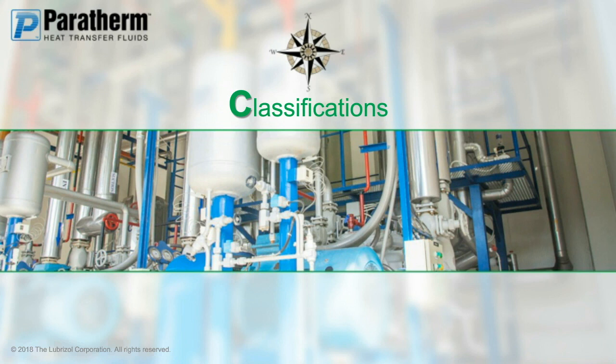Moving from there, we move up the temperature scale, and this is really where we're going to get into our focus because these are the most common hot oil thermal fluids. You're going to have something that could be based on a general classification as a mineral oil, and from the temperature scale going up, you can either have a Group 1 type base fluid. Moving up from there, what would be more ideal in this group would be either Group 2 or Group 2 plus beyond that in the mineral oil area.